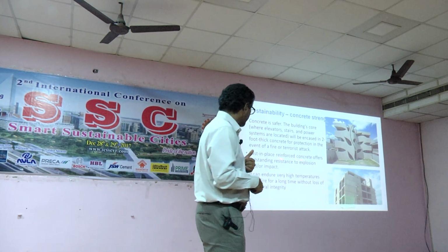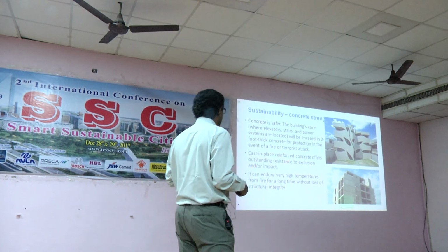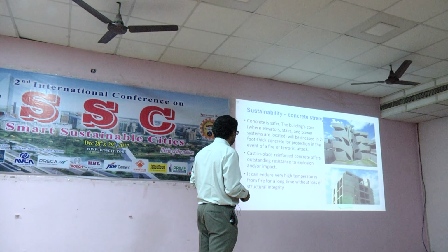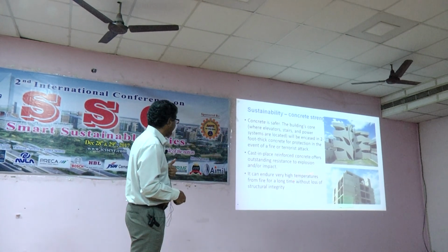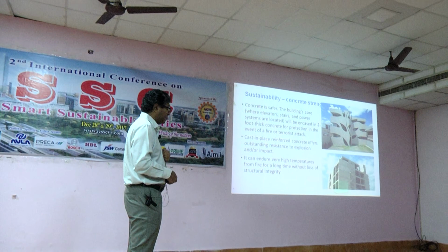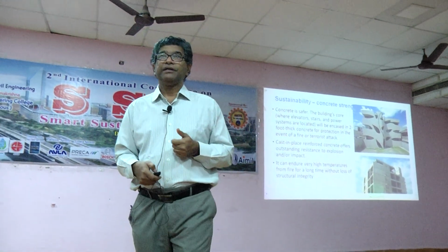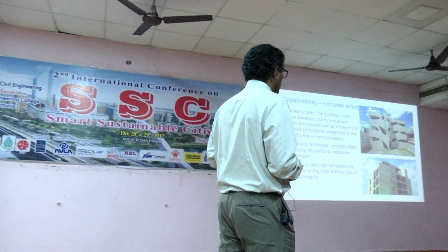So thereby, the concrete element is pretty strong and pretty durable. It will not get cracks or anything else, right? And it has outstanding resistance to explosion and impact, right? It can also endure very high temperature from fire for a long time without loss of structural integrity. From fire also, it has a very fantastic resistance, right? 2 to 4 hours resistance depending upon the thickness of the element that you are going to provide.